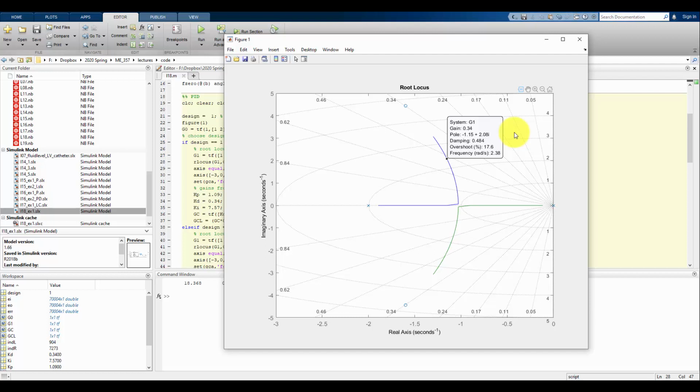That's because I did round a little bit when I put that b in. I only put 4.44. So I'm not going to be able to get exactly the closed loop pole, but this is really as close as I'm going to get, and it's going to be close enough because there are other sources of error anyway. So I'm selecting here a gain of 0.34 to get pretty close to that closed loop transfer function.